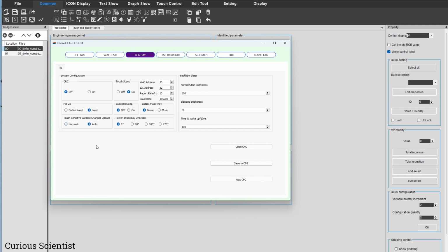So that will allow the code or whatever is behind the display, that will allow the code to send out things to the serial port. So then it has to be auto. And then another thing is the baud rate, which is now this 115200. But I have noticed that if you are using software serial on an Arduino, then this baud rate is not really good. Sometimes you get garbage data or you don't get data at all, so it should be 9600.